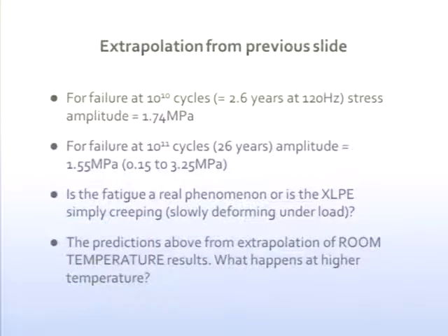So that's sufficient to make the stuff fail after about 26 years. And those are then in the range of the stresses that we've calculated. So the failure mechanism isn't the sort of static loading of the polyethylene, but a cyclic loading of the polyethylene that causes it to have stresses which will fail it.